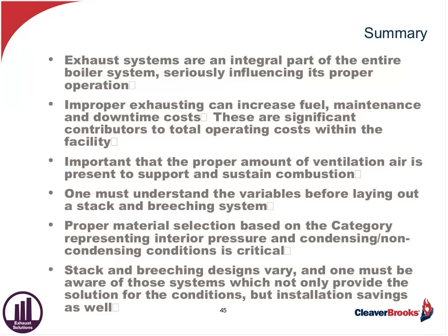So these are the things one must understand, the variables, before laying out a stack and breeching system. Obviously, the proper material selection based on the category becomes important. We went through those today. We stress categories 3 and 4, but of course you may get involved with categories 1 and 2 as well, with atmospheric gas-fired appliances, or where the breeching or stack could become positive, in which case it would be a category 2.